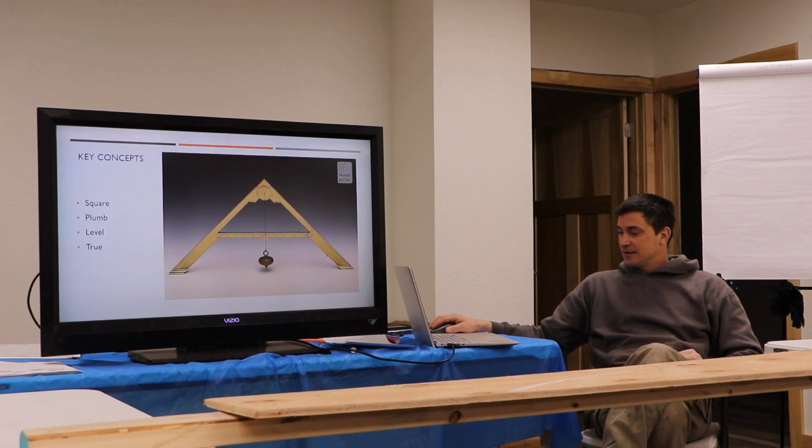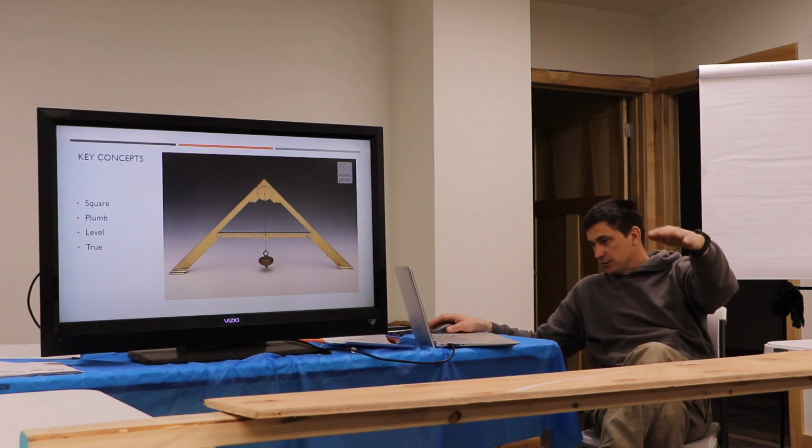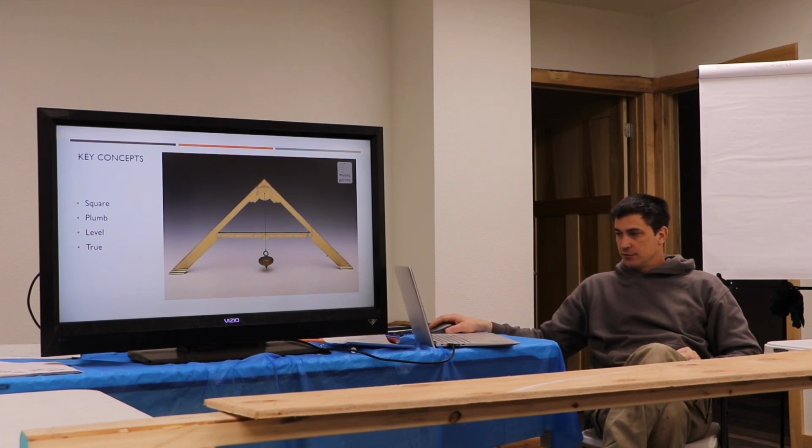So there's a lot of places where we build things that are not level, like we'll taper a garage floor to a drain and all of that. Sometimes we'll build the whole garage floor sloped towards the overhead door if they don't want a floor drain. So there are particular cases where you would build something not level.